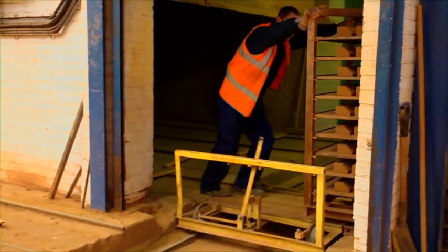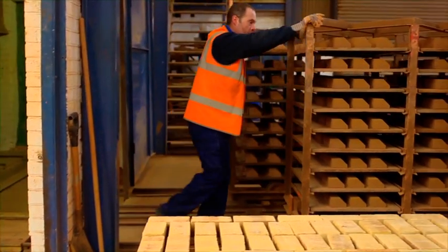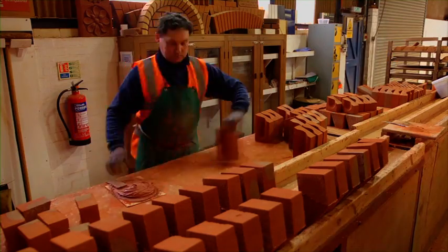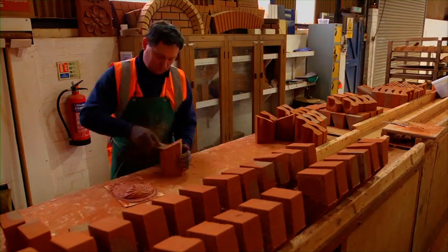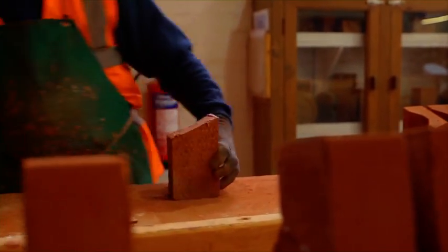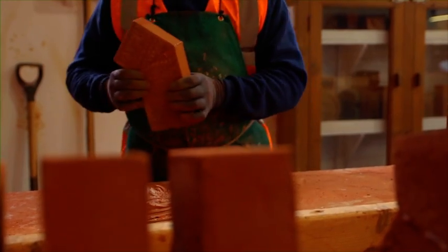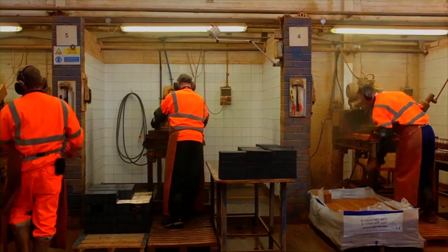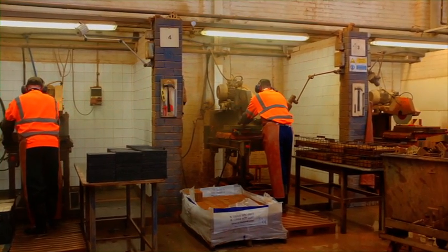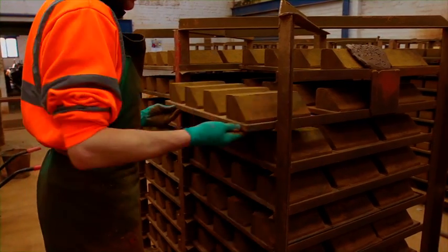Generally, special shapes are manufactured using the same processes as with standard bricks. However, where time or the requirement of a particular shape is an issue, a wide range of shapes can be produced using a method known as cut and bond. Taking regular shaped bricks, cutting them and then sticking them together will sometimes avoid lengthy production times, as well as helping to achieve products impossible to produce using traditional methods. As with all our special shapes, cut and bonded products carry their own guarantee for peace of mind.